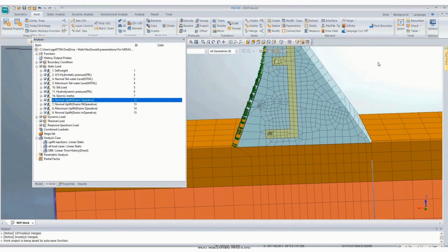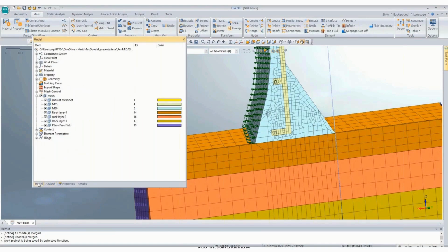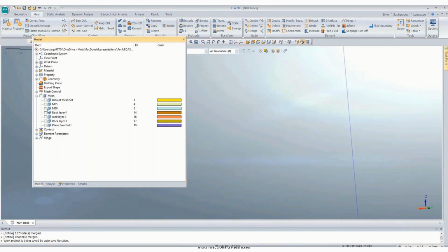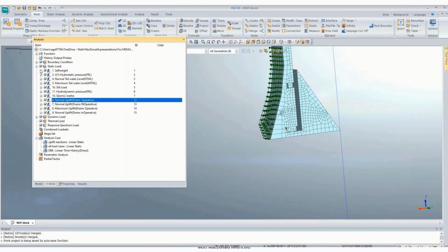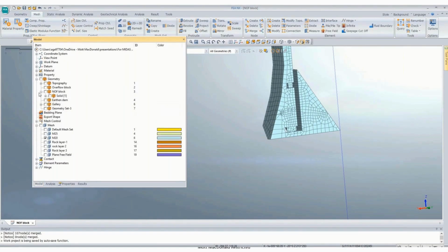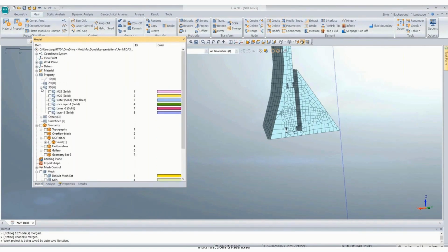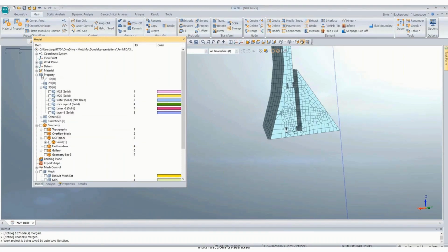So for that again we will repeat the same exercise as we did earlier. So we need only this M20 concrete. We put off these static loads. I have to change the material properties, and go to 3D edit. Oh sorry, materials instead of property.